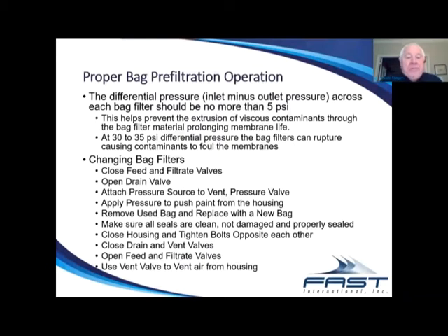Bag filter operation. The best thing to do is always remember to keep an eye on the pressure gauges on the bag filters, the individual bag filters, not necessarily one at the beginning and one at the end of the bag filter manifold. And that should be no more than 5 psi differential. That is the difference between the inlet pressure minus the outlet pressure.